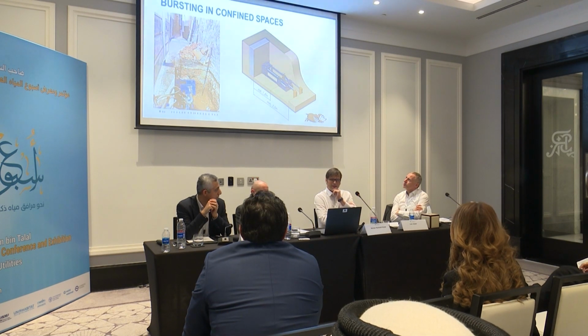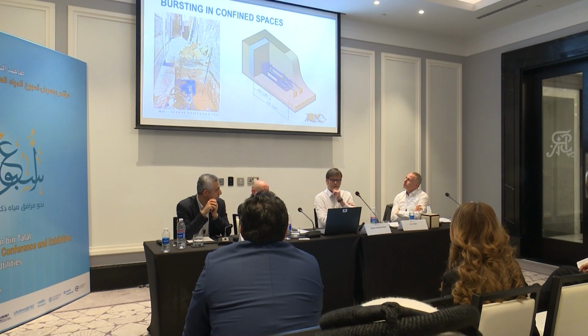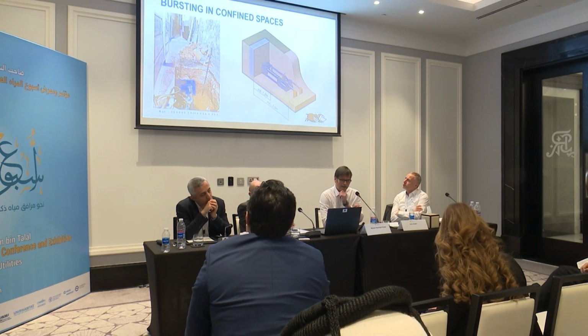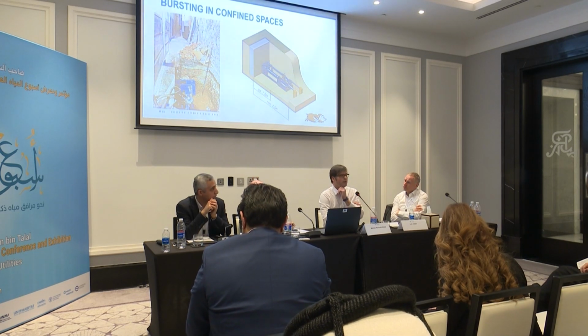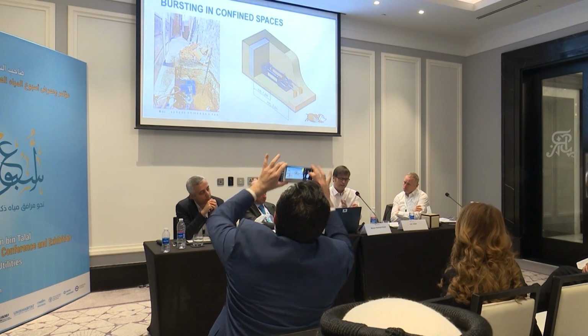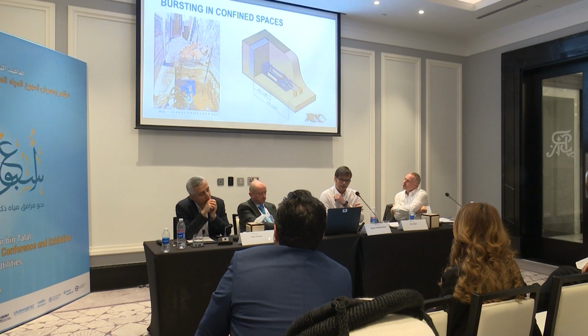Now this is a little job. I was looking for some jobs that we've actually done in the region, and this pipe burst was actually done with our smallest pipe bursting rig, a 40-ton rig, in Rabat in Morocco. In the old town, and you can see the restrictions that we had there with regards to space. The pit was only 2.5 meters long.